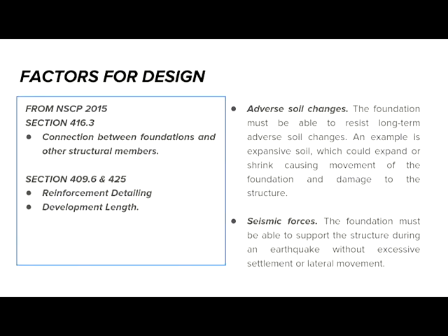Next, we have to consider adverse soil changes. The foundation must be able to resist long-term adverse soil changes. An example is an expansive soil, which could expand or shrink, causing movement of the foundation and damage to the structure. So we also need to consider the unpredictability of the soil when designing a foundation. Next, seismic forces. The foundation must be able to support the structure during an earthquake without excessive settlement or lateral movement.